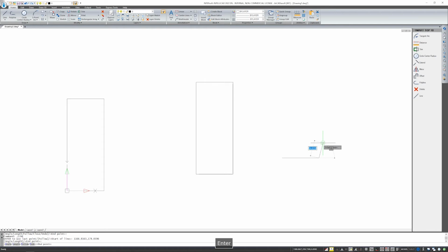And now in the same way, I can enter the whole rectangle. So again, 500. I switch to the angle, I enter 90. Note that when I enter data in this way, sometimes the program treats the angle relatively. So when you define the end after switching, always check the setting of the angle.